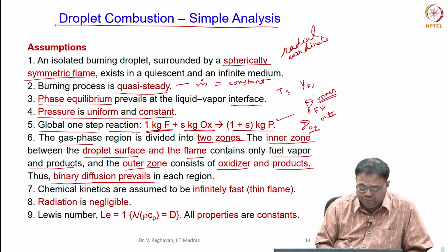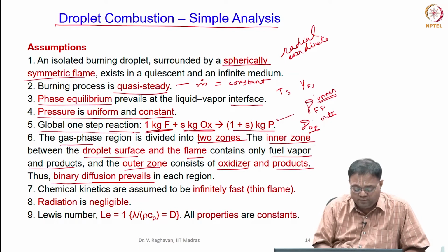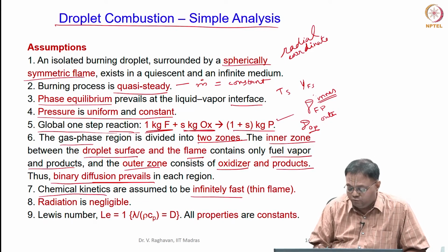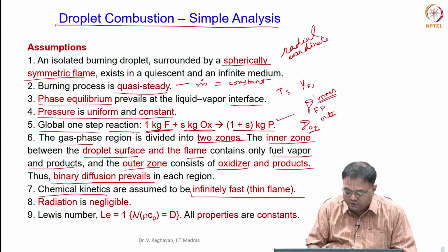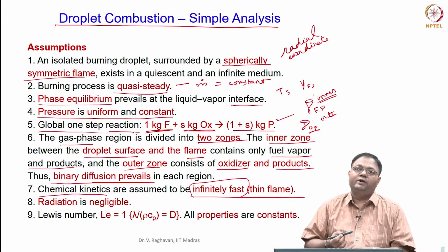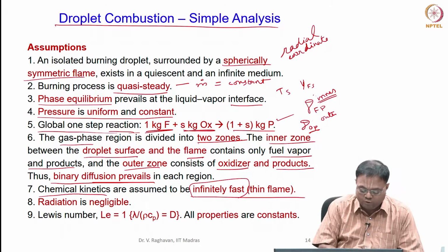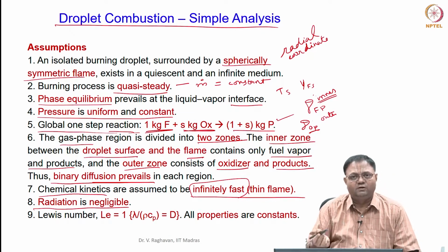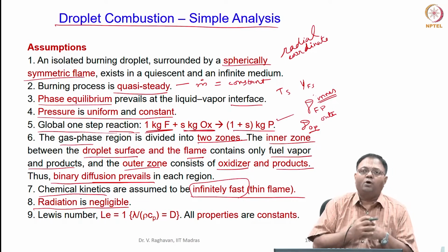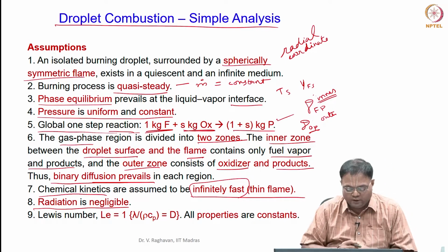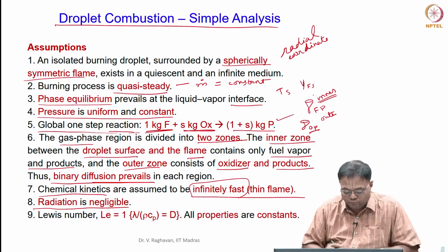Then, in order to get rid of chemistry, I assume that the flame is very thin and the chemical reaction or kinetics is infinitely fast, and I do not take radiation into account, which is negligible. In fact, the heat addition to the droplet is predominantly by conduction only. So, we can neglect the radiation.